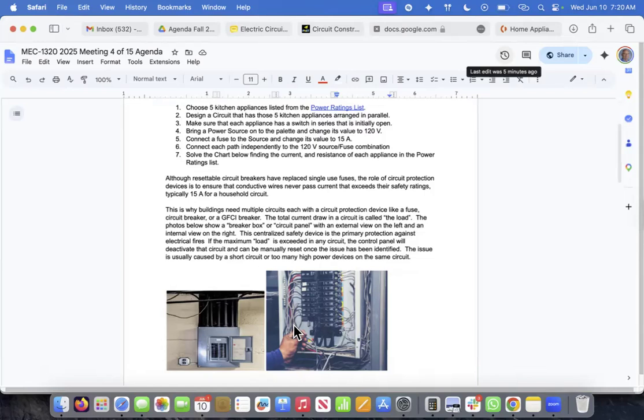And that, number one, makes them more efficient. And number two, it reduces the load so it doesn't approach the maximum current that's capable of being passed through these wires without causing excessive heating. That heating, again, was going to reduce efficiency, but also poses a danger in starting fires.